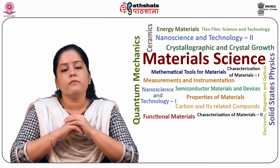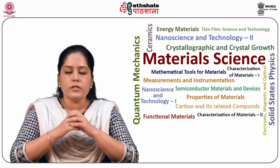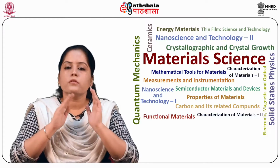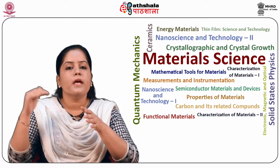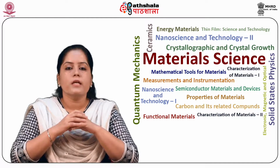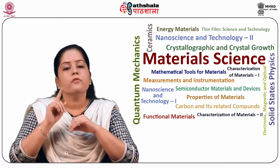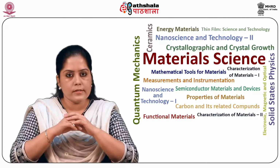A second possible reliability problem that can occur is the deconfinement of the two-dimensional electron gas, 2DEG, under high temperature conditions. Thermally accelerated testing has shown that aluminium can migrate laterally into the gate, resulting in a change in the conduction band discontinuity. So the advantages of MODFET are: first, they have high gain, making them useful as amplifiers.